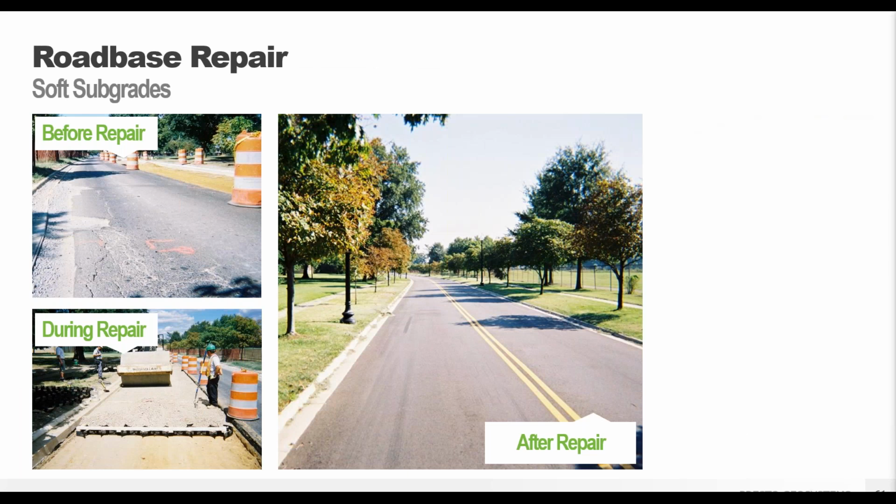I'm sure we've all dealt with roads like this. So surface cracking, ruts, lots of patched up areas that seem to start failing almost immediately. This is what happens when the road is built over that weak base layer that can't fully support the vehicle traffic. With the GeoWeb system, the failed asphalt and base layers are removed, the GeoWeb panels are laid down and filled in with a granular material, and then you have a fresh paved surface over top of the panels.